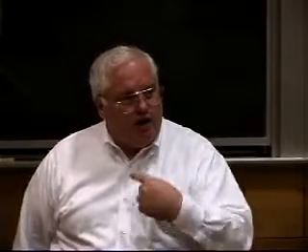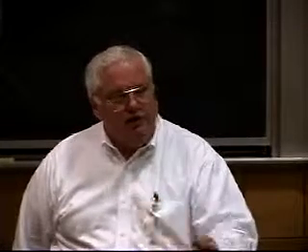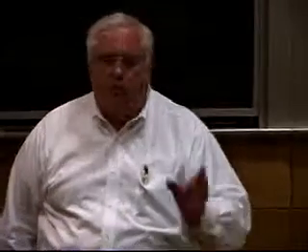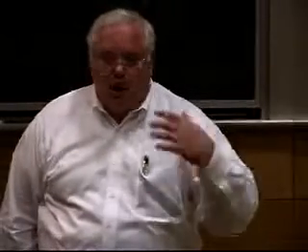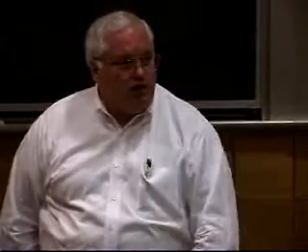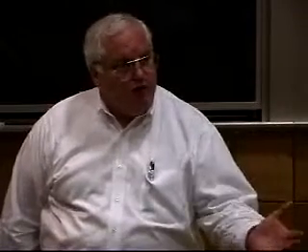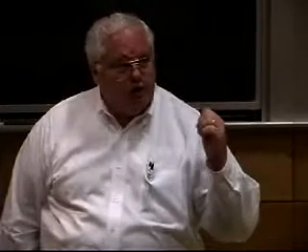You cannot use directly the Charpy fracture energy in a fracture mechanics calculation. What you need is the KSI square root of inch number. There are correlations, they're not perfect, and people still argue. Academics argue until they're blue in the face about are the correlations any good? Well, they're better than nothing if all you got is a Charpy value. And usually all you have is a Charpy value if you're talking industrially, because a K1C test is not $70, it's a couple $1,000.